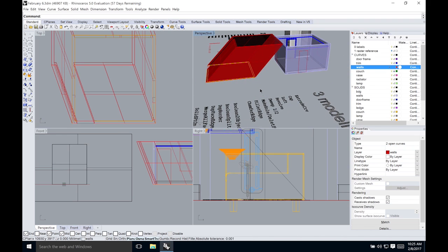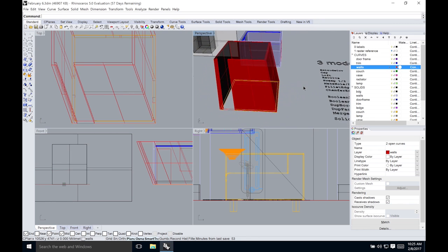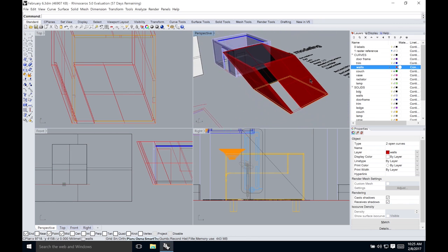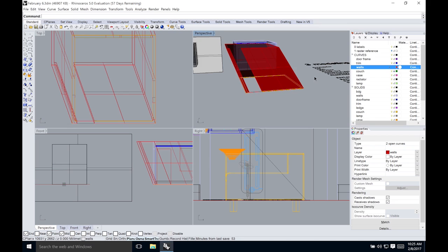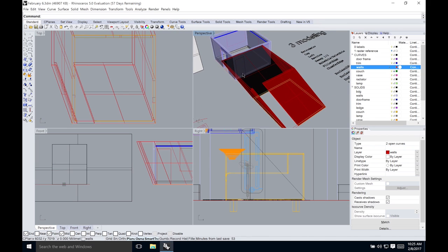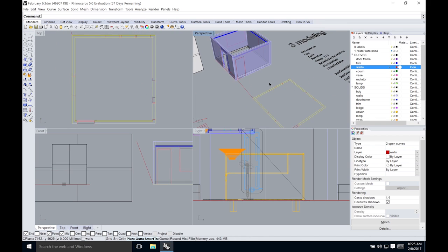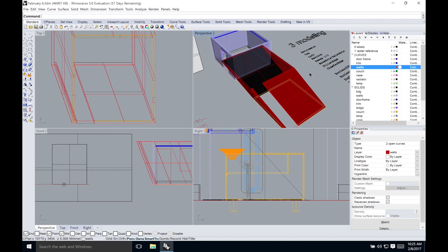And again, I don't think that this would be the first thing that you would have to deal with in your assignment, but it's good to know that extrude always works perpendicular to whatever construction plane you're working with, and this is a way to tell Rhino exactly which direction you want to extrude. Actually, I'll leave this here.